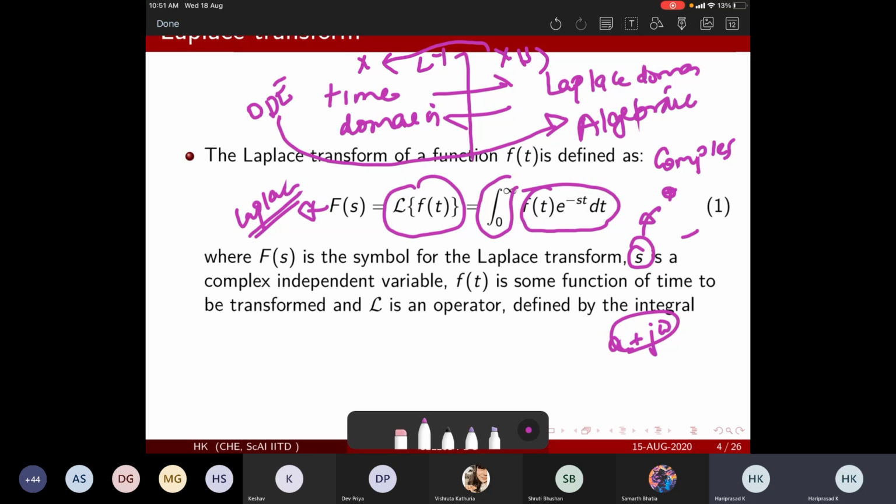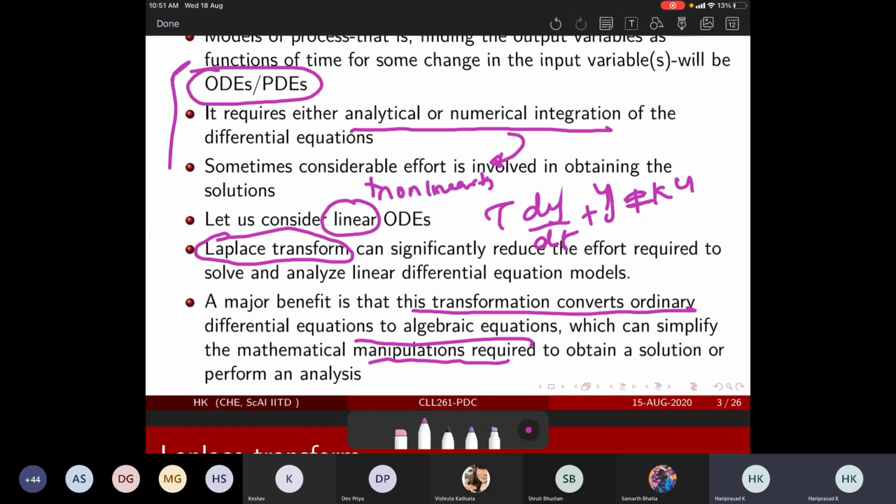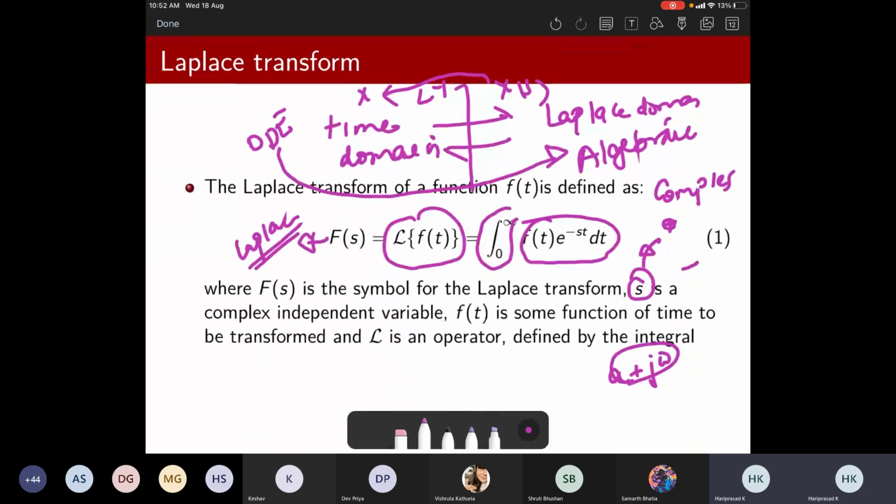Anyway, when you need to do control, you have to deal with complex ODEs and PDEs, which is difficult to deal with considering this aspect. So let's not do the analysis in the ODE space, even though they represent the dynamics, because of its complexity. Let's move ahead to a regime where you have much more freedom to play around. Once you have the ODEs, you don't do any further analysis. You convert them into the Laplace domain, so things become algebraic, and whatever you could do is much easier to figure out.